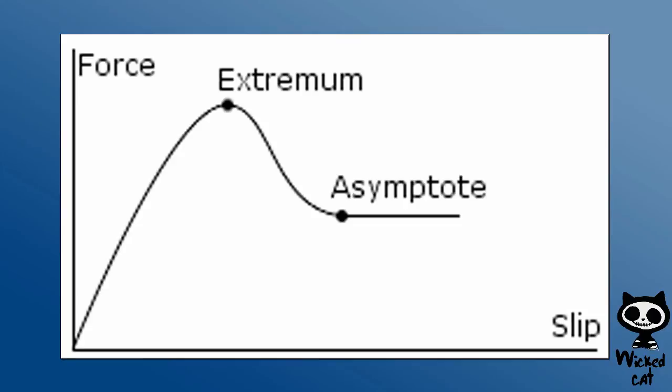Then, the curve takes a measure of tire slip as an input and gives a force as output. Real tires can exert high forces for low slip, since the rubber compensates for the slip by stretching. When the slip gets really high, the forces are reduced as the tire starts to slide or spin. Because of this, the tire friction curves look a lot like this graphic.